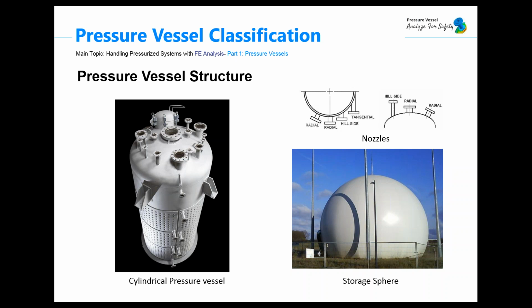Depending on the type and purpose of the pressure vessel, they have some number of openings, especially if we take a look at this pressure vessel on the left. Openings in pressure vessels are necessary to carry on normal operations, and they allow for mounting of equipment, the insertion of instrumentation, and the connection of piping to facilitate the introduction and extraction of content. Openings are generally made in both vessel shells as well as heads, as you see in the picture.